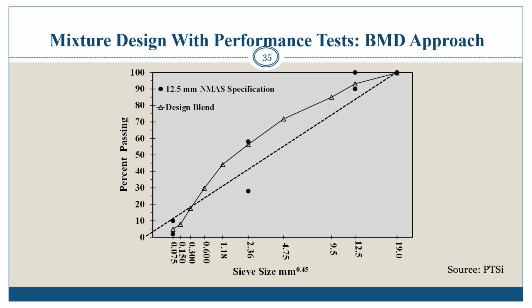DGA, or dense graded asphalt, is a common mixture type used in asphalt pavement construction. It is widely used as a base course, binder course, and a surface course. So you can see it could be used quite often, and so it's a mix that could have a lot of uses for GTR modified binders. Again, it's suggested that use of GTR modified binders avoid gradations such as the one in this diagram.